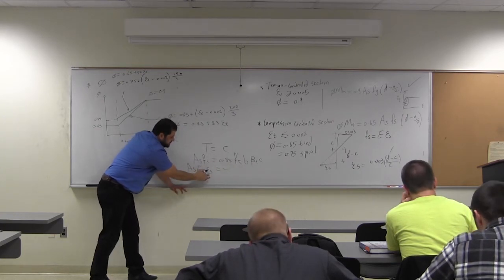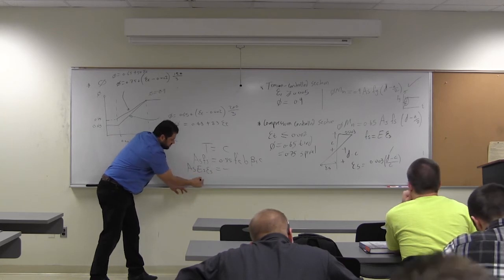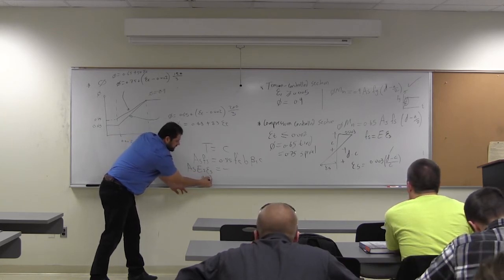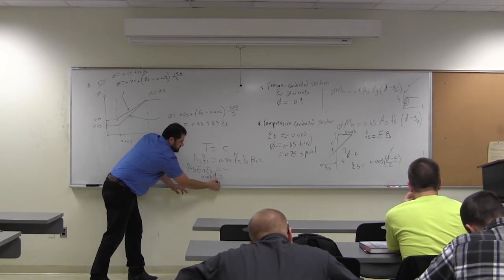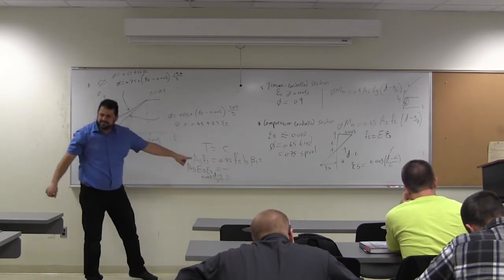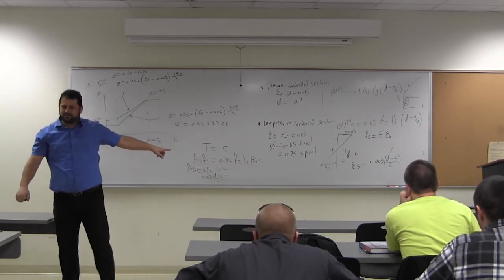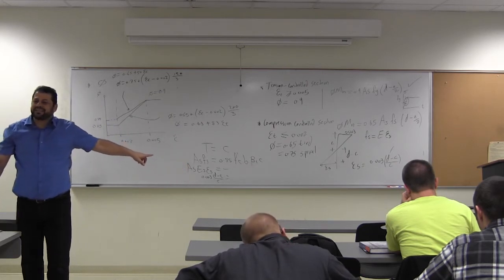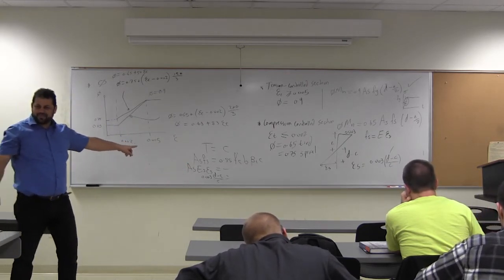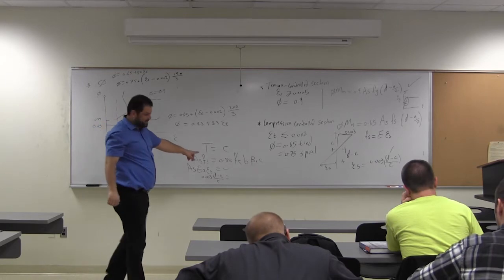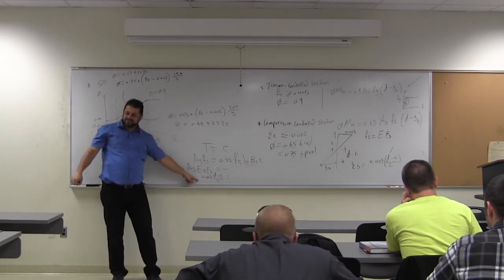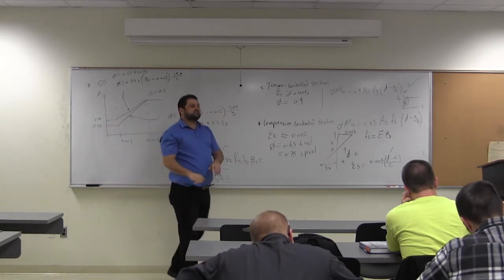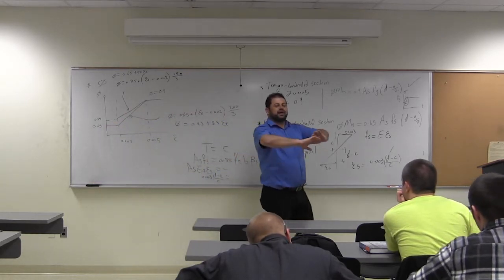What's epsilon S? 0.003 (D minus C) over C equals that. Is it an easy equation, Paul? You good with math? That's a quadratic equation with C. We need to solve a quadratic equation for C. Once you get C, you get A, you do that. That's compression analysis. That's for analysis.